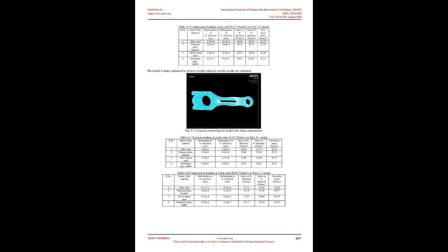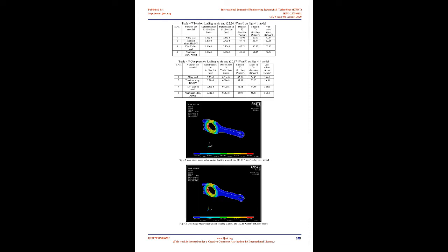2. Literature survey. The connecting rod is an important component that needs a typical analysis of its structural stability under dynamic conditions. It is also critical to maintain an optimum weight to strength ratio to sustain inertial loads. Shape optimization is needed to reduce inertial load, thus minimizing the internal stresses during dynamic conditions. Loading conditions are chosen at the crank end and pin end to analyze the von Mises stresses, and shape optimization is carried out randomly to reduce the weight of the component.